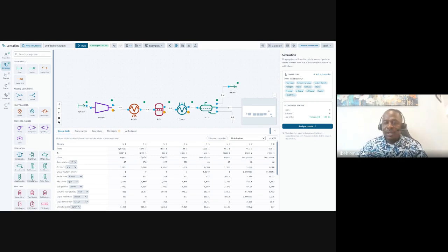The separator unit is still online, connected, and functional. If we feed 200 degrees Celsius hot gas into it, what do you think we'll get in our liquid fuel product S7? If I put a very high temperature into it, what are we going to get? Let's play around with that together. Where you have that cooler, remember the cooler is cooling to 40 degrees centigrade. Now change the temperature of the cooler to 200. So let's go and do that.